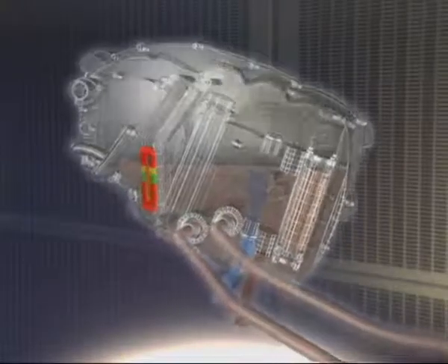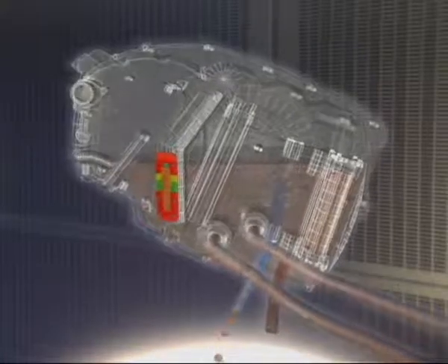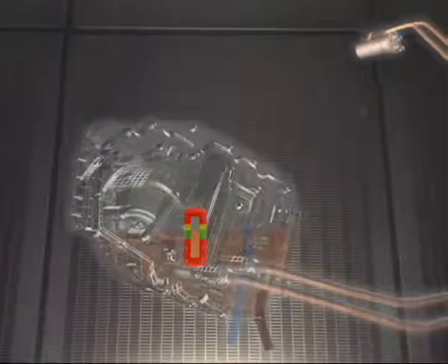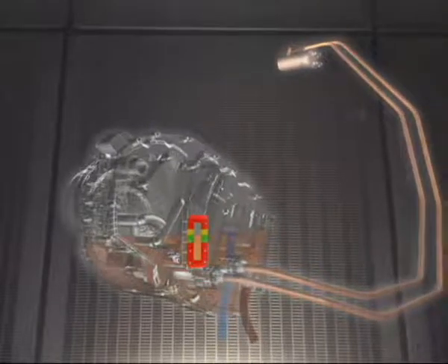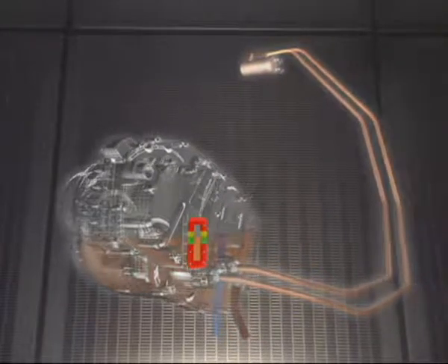Now the IDG case is being filled with oil. Once the oil level exceeds the top of the overflow standpipe, it flows outside the IDG through the overflow drain port. The top of the overflow standpipe corresponds to the top of the green band of the sight glass. The servicing procedure is aimed at filling all the cavities of the circuit with oil, expelling air pockets, and thus setting the optimum oil level.